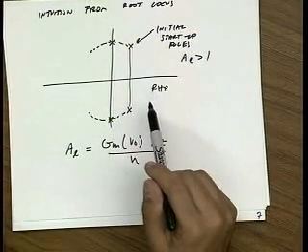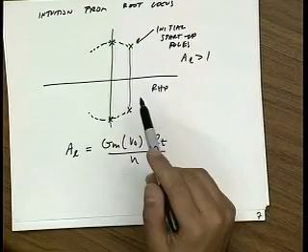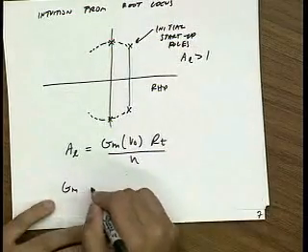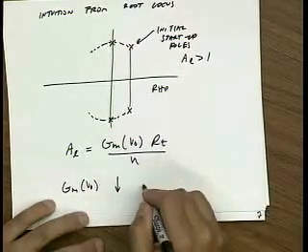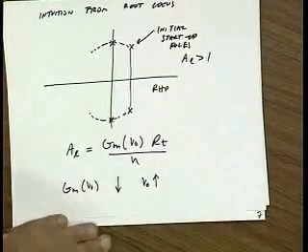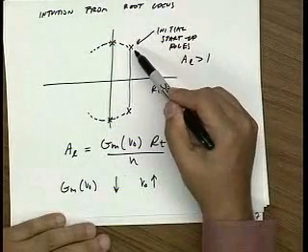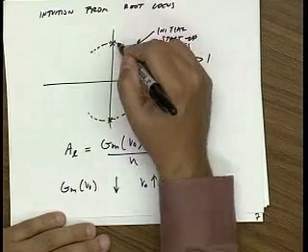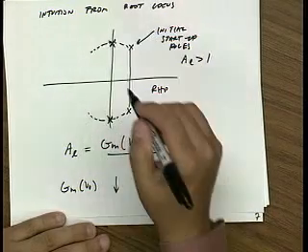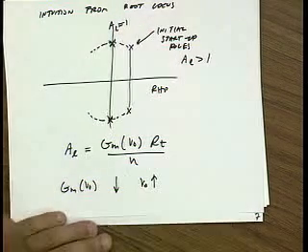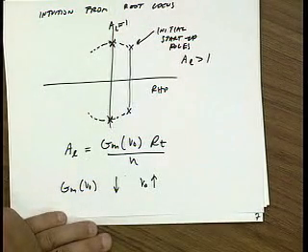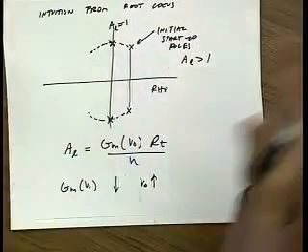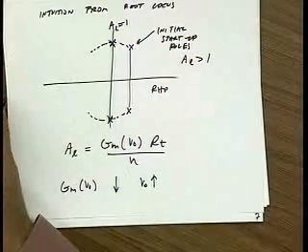So as the oscillation amplitude gets bigger and bigger, the Gm gets smaller and smaller, right? So Gm as a function of VO goes down as VO goes up. That means that as the amplitude grows, the poles move to the left. And when they hit the j omega axis, loop gain is exactly equal to 1, and they just stay there. Because once they hit the j omega axis, the poles don't grow and they don't decay. So they just remain constant, right?